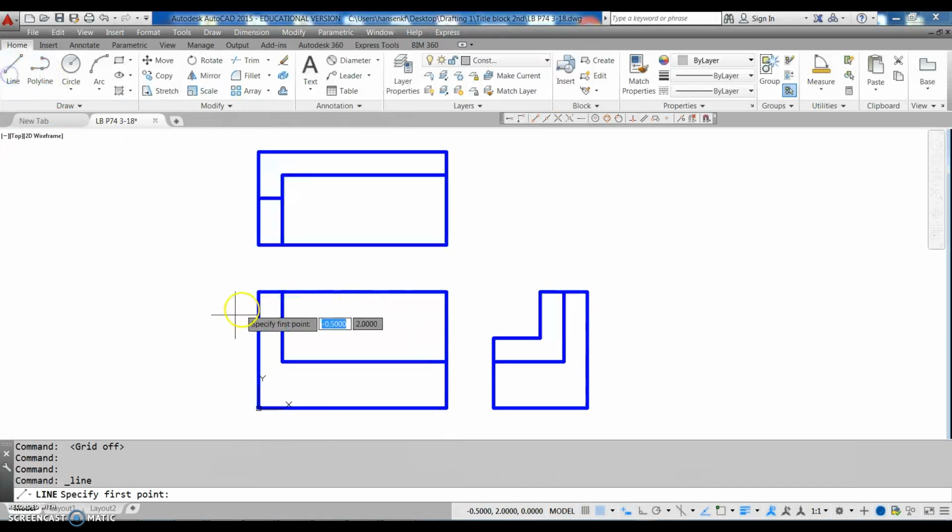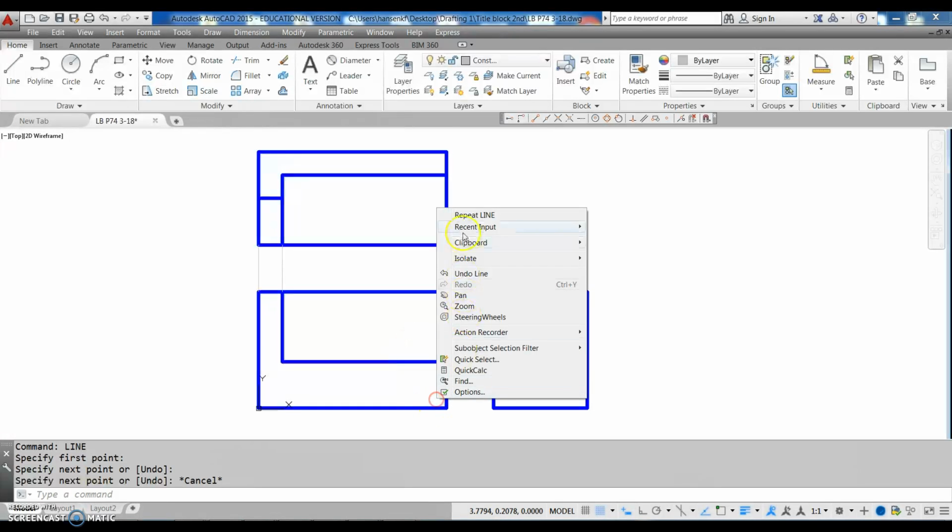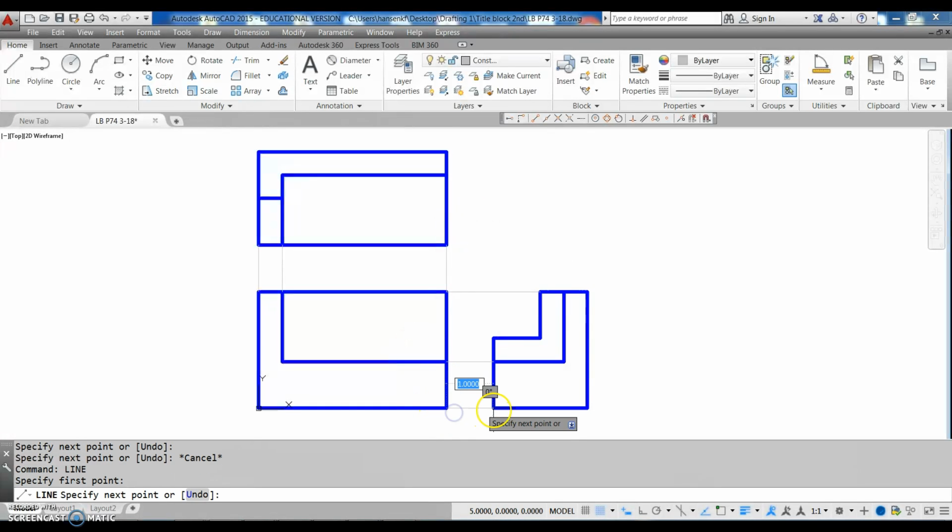The construction line layer is basically just so you can draw on your drawing without having the lines appear or be saved or printed when you are finishing your drawing. So if you look at this, what I'm doing here is just showing you that everything that I have drawn in my front view lines up with my right side view or my top view.